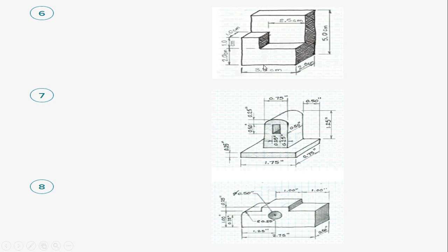Now there are two different methods of part creation in Autodesk Inventor. It is additive and subtractive. So in this case, we are going to do the subtractive method. We are going to draw a large rectangular prism, and then we are going to cut this little surface back here out to create these two ledges. So when we go back to our part, we're going to know the full dimensions of the object: 3.5 centimeters wide, 5 centimeters tall, 2 centimeters deep.